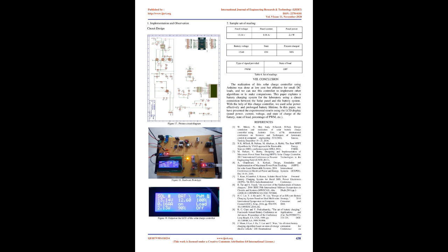4. IR2104 MOSFET driver. A microcontroller cannot turn on a MOSFET as it cannot supply enough current to charge the MOSFET, because the gate of the MOSFET is capacitive in nature. That is why a MOSFET driver is required. The driver itself will supply the current that the MOSFET will need. As we are using a buck converter, the PWM signal will be applied with respect to the MOSFET source. That is why the MOSFET driver will also provide ground isolation capabilities so that the source of the MOSFET and ground are not shorted. We have used 2 optocouplers to form the driver.